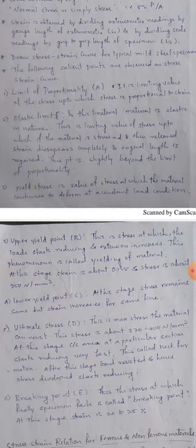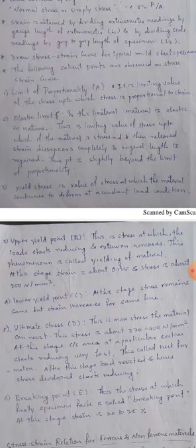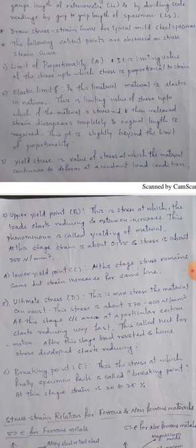And at a lower yield point, the stress remains the same, but strain increases for the same line. If you consider D, that is the last one, ultimate stress. This is the maximum stress. The material can resist this stress up to 370 to 400 Newton per mm square. These are possible standard values. And the breaking point, of course, is the stress at which the specimen finally fails. At this stage, the strain becomes 20 to 25%.